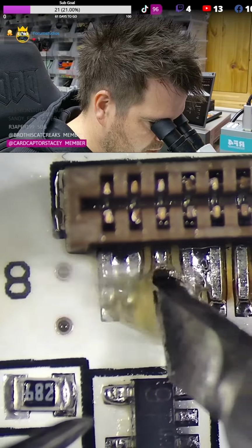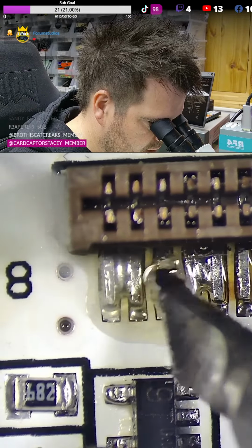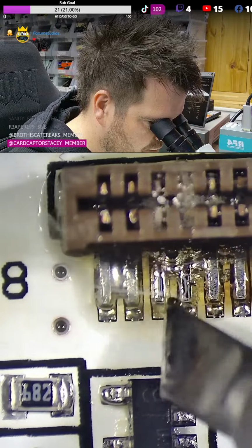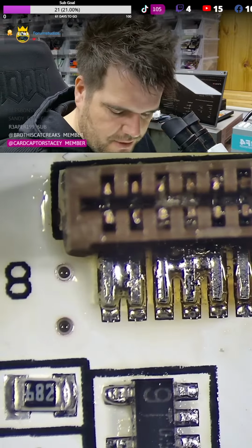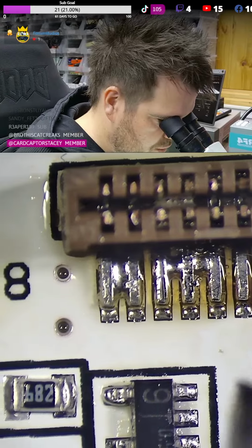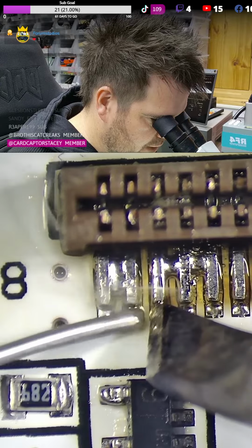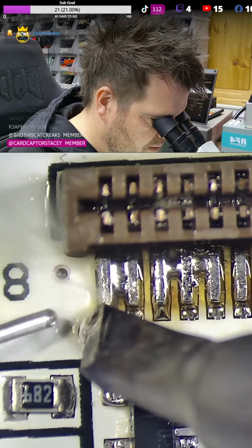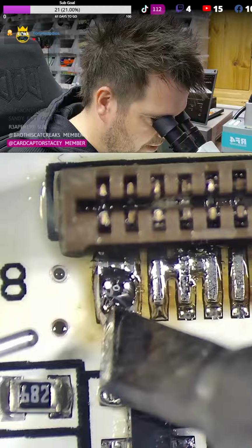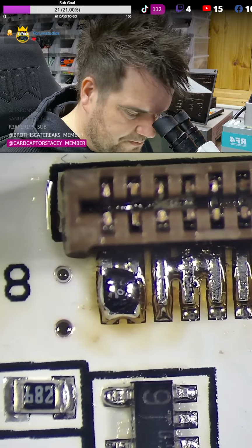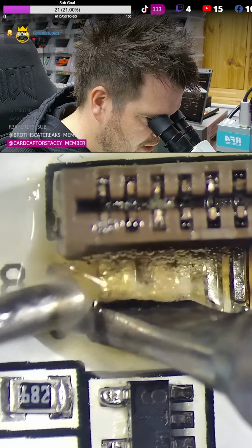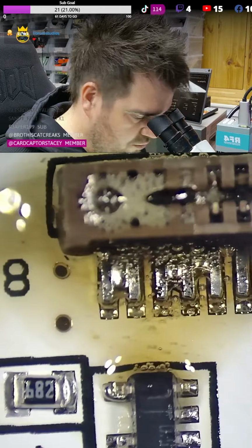So we're going to go back in with flux, try and steal some solder from this connector and get it to bridge over. If it doesn't want to bridge over, just add a bit more. But the goal is, you can see how it's gone shiny now, but you can add a tiny bit more and get the pads nice and round. And it's mainly getting the heat down to the pads. And then once you've got plenty of solder on, now the job is to remove these bridges.